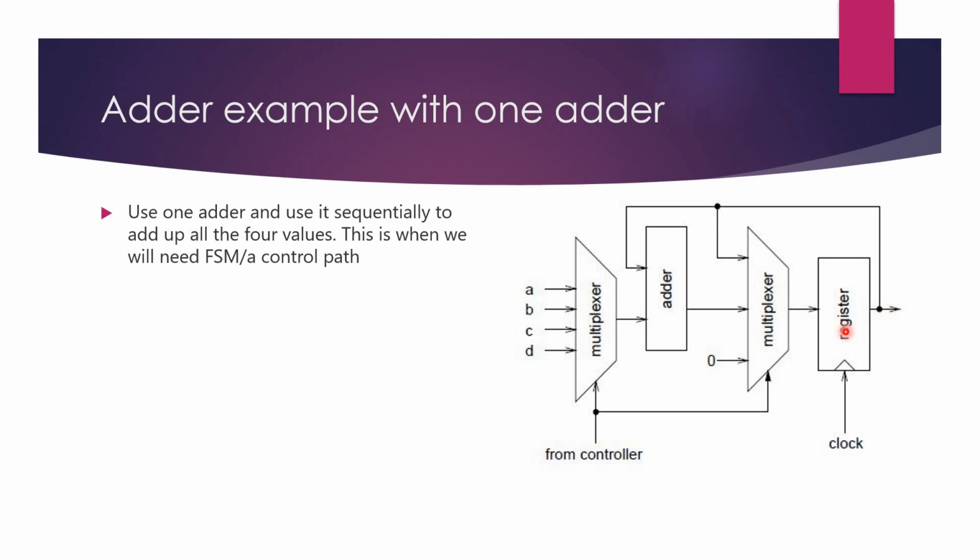Draw the diagram for your own practice. That's how you understand the design. These are secrets I'm telling you, right? Nobody will teach you this in academics. That's how you learn to analyze a circuit. Once you can analyze a circuit, you know how to design. That's how you solve problems. So draw a timing diagram in your own interest and understand how the input goes to the output, clock by clock, with all the internal node values.